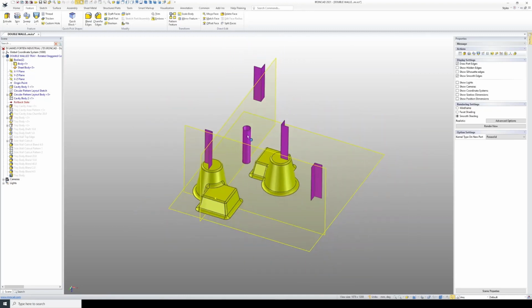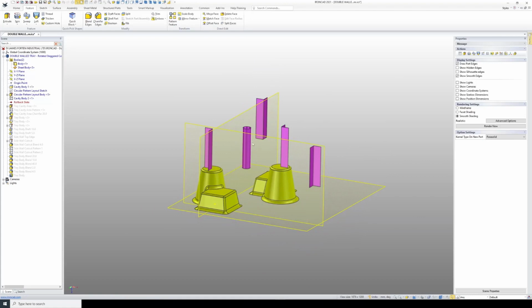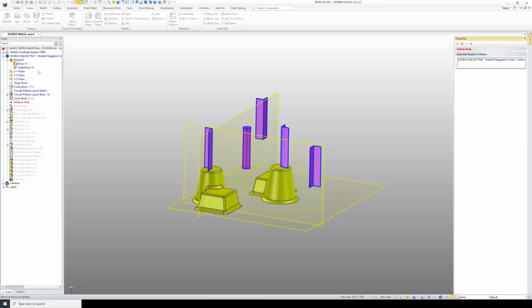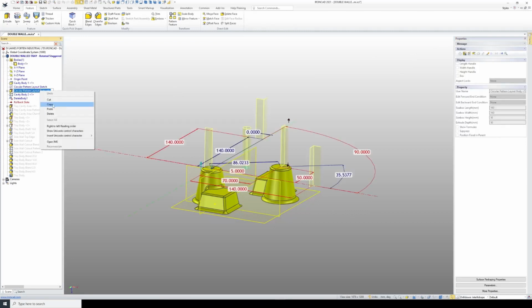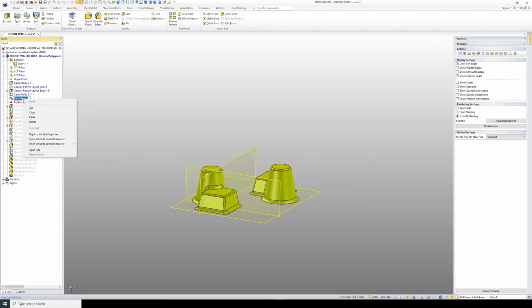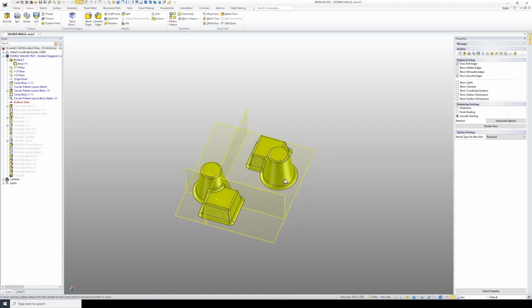Well, actually, first thing is that I don't need this body anymore. So select the body, the sheet body, right click on it and go delete body, and then OK. And we'll give a name to that. So I'll just copy and paste here, and I'll put delete here. So again, it's to help me recognize that I've just deleted body 5. And now to demonstrate that sketch.